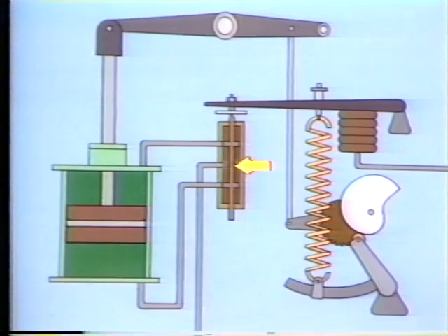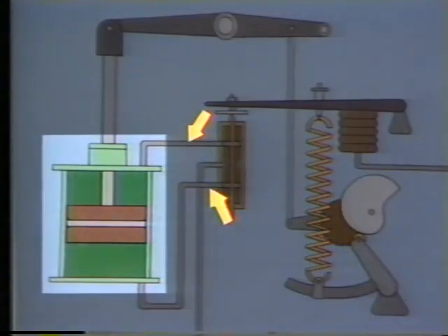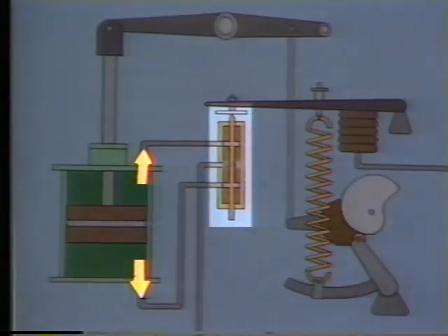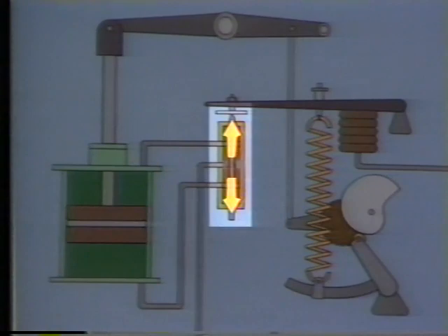There is also a valve stem that has 2 discs on it that moves inside the valve body. The 2 discs serve as plugs, which allow air to enter or leave the actuator through these air pressure lines that are connected to the actuator. Air that leaves the actuator is exhausted to the pilot valve and out through here, where the valve stem moves through the valve body.